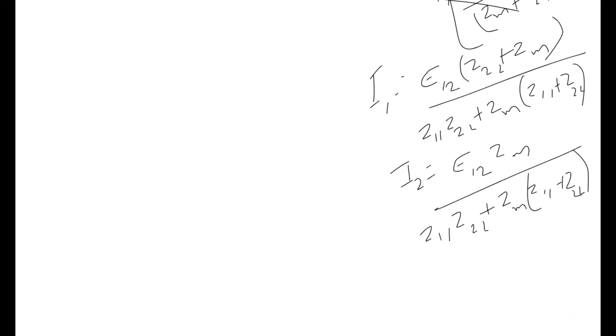And next is ultra high frequency. What is the full form of UHF? Ultra high frequency, ranging from 300 to 3000 megahertz. In these two frequency ranges, it works and obeys the characteristics of circular polarization. These are the points we have to cover. And this is useful for extraterrestrial communications like satellites and relays. We use these types of antennas.